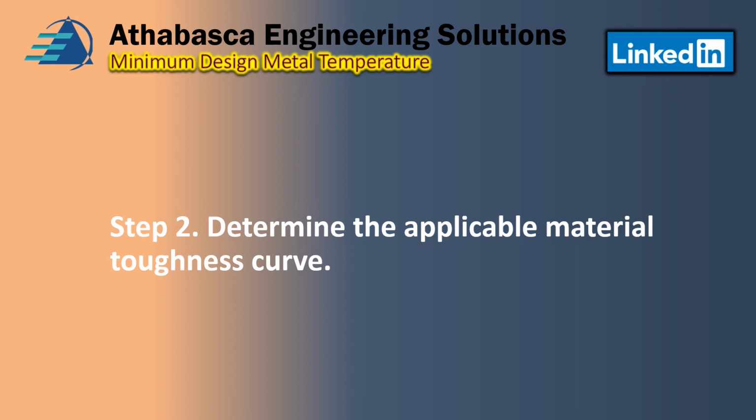So you can see that this is a little bit more in-depth of an analysis than Division 1, where you can take advantage of the post-weld heat treat code or not, whereas the rules are a little bit more general in Division 1. So let's continue.